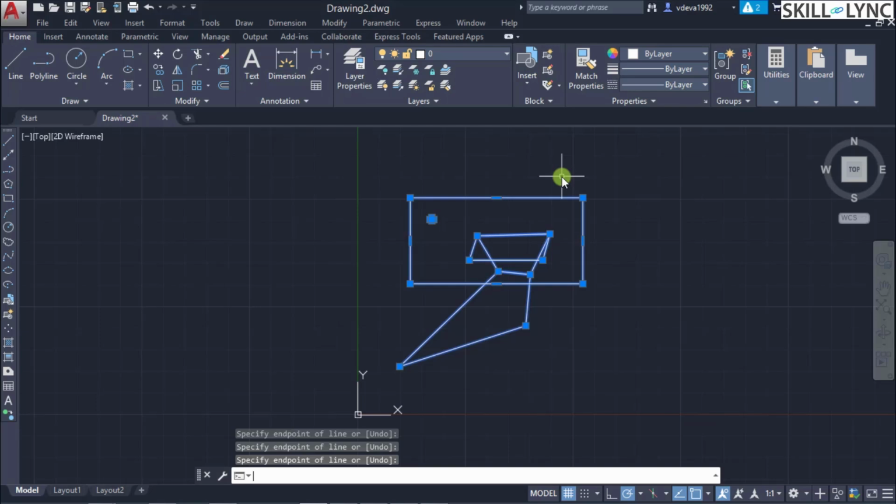So typically you have to be sure of what selection you intend to make, whether it's inside the selection area or passing through the selection area as a whole. Based on that, you get a designated blue space or a green space, and by default you have a box command, that is a rectangular command. And if you want to go for multitude selection, then you can go for a polygon based one.